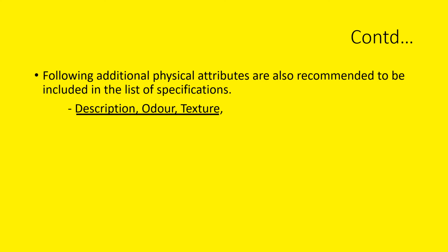The test method should include the intricate details. The section prescribes the perception of color and color matches is dependent on the conditions of viewing and illumination. Determinations should be made using diffuse uniform illumination under conditions that reduce shadows and non-spectral reflectance to a minimum.